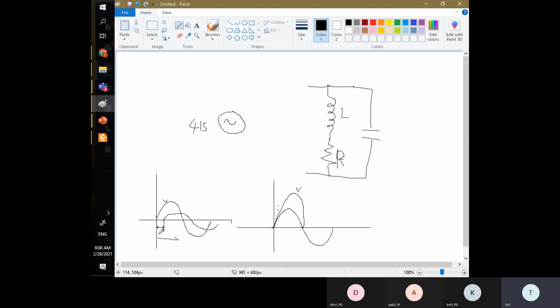Usually it's called the delta. So this is a current. You can see the voltage first rises up. Sometime later, the current also follows going up, right? When the voltage goes below 0, the current still has not gone below 0. The current is going to take a while, then go below 0. So they are not in phase.